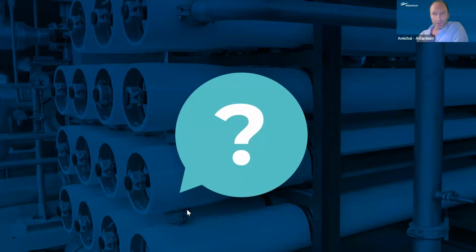Okay, last question I see here. How can system operators ensure optimal performance? I think like in most cases, when using ORP, and I think Itzik addressed a similar question. When using an ORP after the UV or using some chlorine meter, in most cases people use ORP even though it's not a direct measurement. And when the UV requires some maintenance, you would not see breakthrough of chlorine. You would see a small change. The ORP will go a little bit higher, but it won't go to breakthrough.